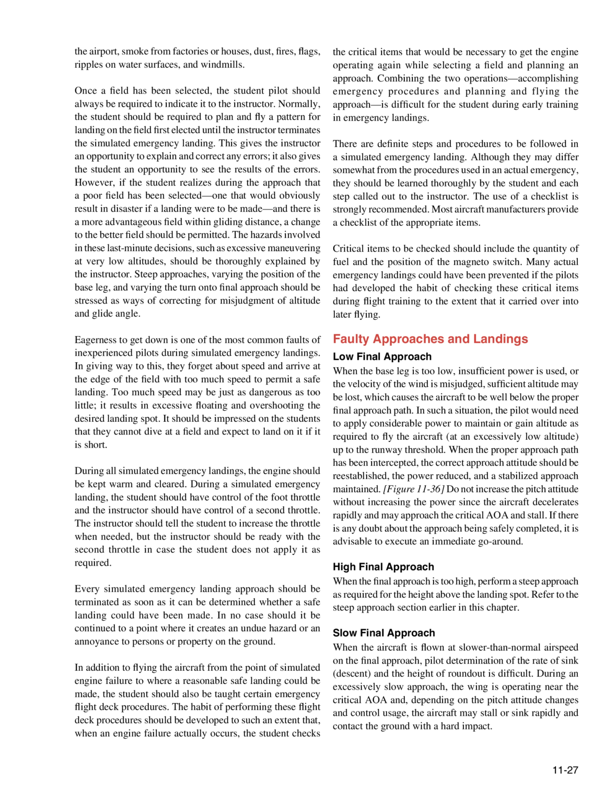Faulty approaches and landings. Low final approach: when the base leg is too low, insufficient power is used, or the velocity of the wind is misjudged, sufficient altitude may be lost, which causes the aircraft to be well below the proper final approach path.